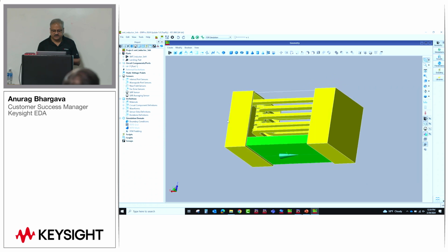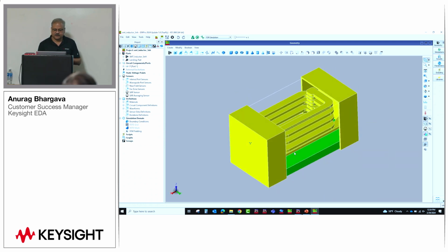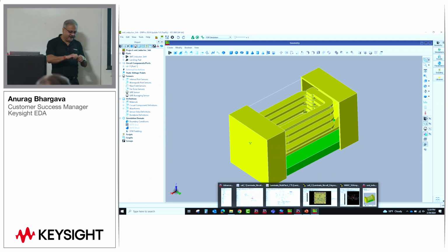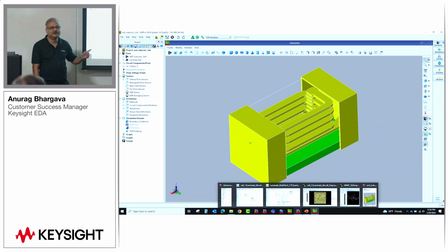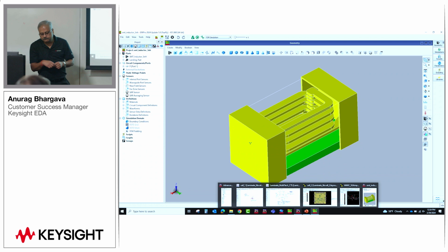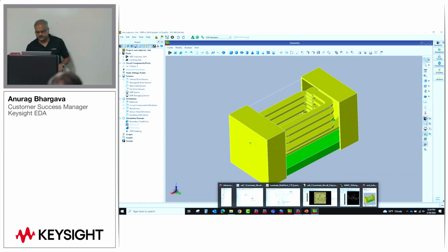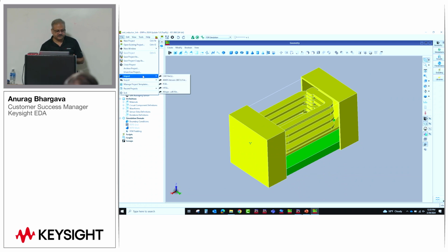And now here you can see this is a 3D model for an inductor, which is how, if you have not ever cracked open your SMT inductor and looked under a microscope, the internals of any SMD inductor look. So you have those windings, and it is offering a certain inductance. So once you have it, if you have your own third party HFSS file, you can see it has an HFSS import option.